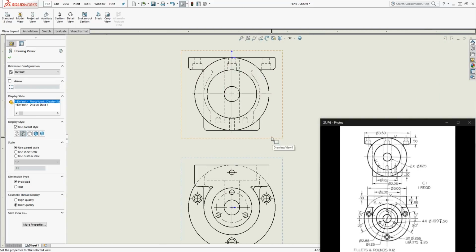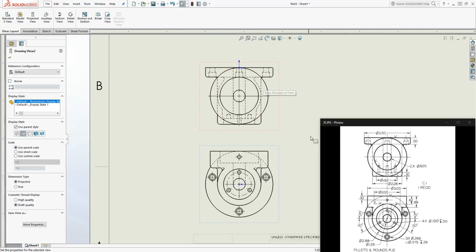And as you can see, you have all your features. So you can see the hidden lines are matching up. That's a good way to verify your work. Your hidden lines should match up. So all the hidden lines are matched up, and you have your circle over there. You have the circle at the top. Those two. So if you were to dimension it, it would be right. So this is pretty much how you make this part.